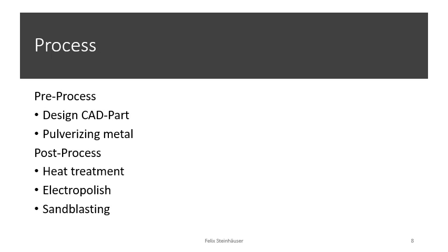Then for a surface finish you could electropolish it, which smoothes the surface, but you also could color it with anodizing, or for finishing the surface use sandblasting. Sandblasting not just smoothens or roughens the surface, it also helps to remove some of the excess metal powder. So these are the steps you need to consider around the process.